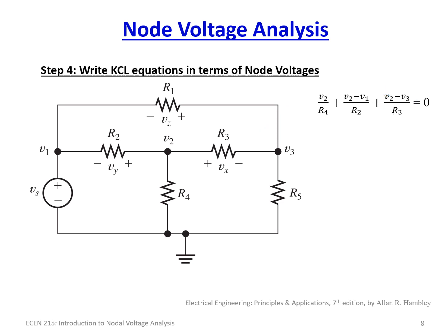Okay, just to slow this down a little bit, in case you're slightly confused: we write the KCL equation for one of the nodes. We're going to start with this node here, V2. There are only 3 possible ways current can enter or leave the node, and again, I'm using leaving as positive. So we start with this. We're going to call this I1, I2, and I3. Don't get this confused with node 1, 2, and 3. It's just arbitrary.